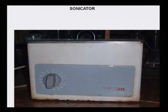Now comes the Sonicator. This is the machine which uses ultrasound energy, and ultrasound energy of 20 kilohertz frequency at a wattage of about 50 can create agitation which can be very good for extracting the colorant from the plant material. This was used for the first time in our laboratory while we were working with some natural dyes.